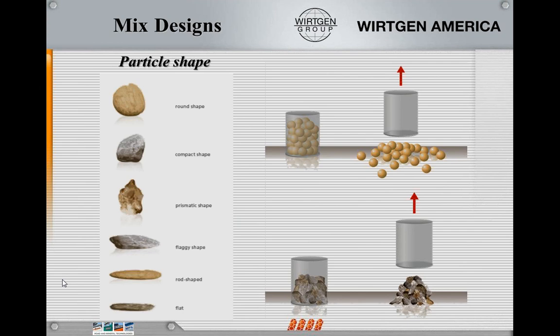If we have an open aggregate spot, I have a tendency to maybe force some water in there, separate the oil from the rock, and we can get some stripping. So we've got to be careful on how much that is.